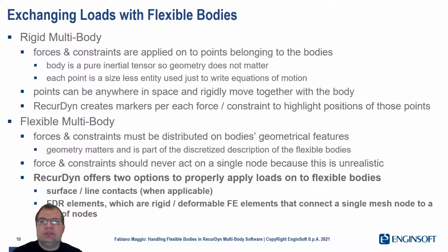The other aspect dealing with flexible bodies and flexible multi-body simulation is the way that the loads are transferred to the bodies. If you are in rigid multi-body, each body is an abstract entity. As said, it's just a reference marker with certain properties, inertial moments, moving in space, and you can imagine that any point belonging to that body can be used to apply a load, and there is no relation with the geometry that you had to extract the inertial properties.